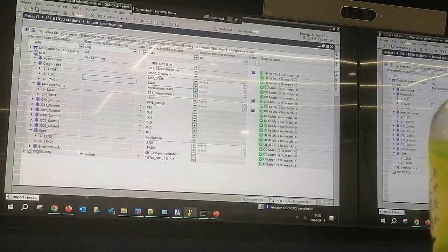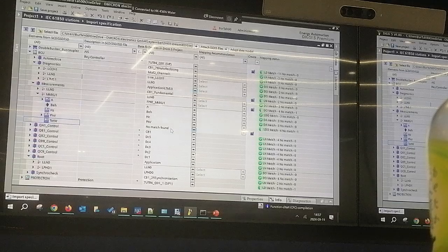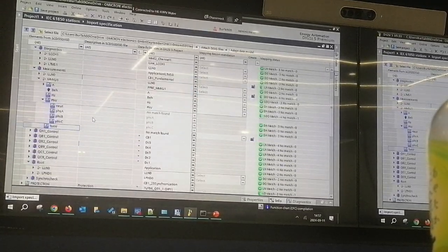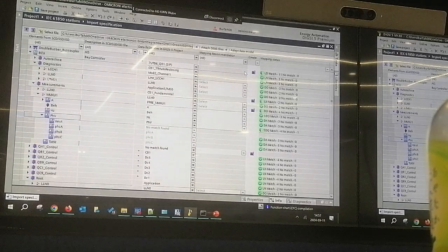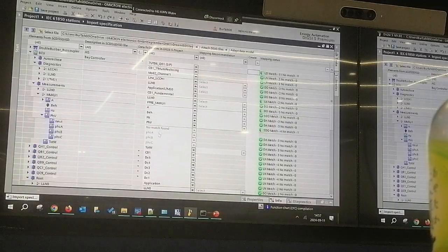In the measurement I have a problem. This is my mistake. I tell you why. What he couldn't find is this total watt. Maybe this is not in the file. This is just A. And the problem is phase to neutral voltage. I defined neutral. This is funny. You have phase to neutral and neutral voltage. This is not possible in this. You need another logical node. Okay. So with that, if I click this, then my IED is 100% matching.